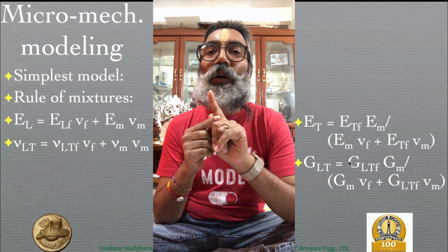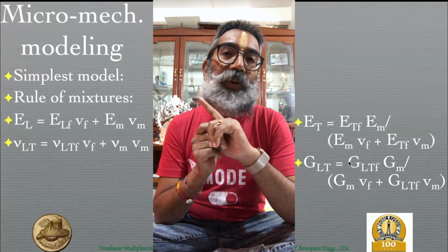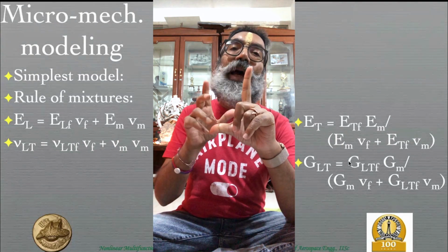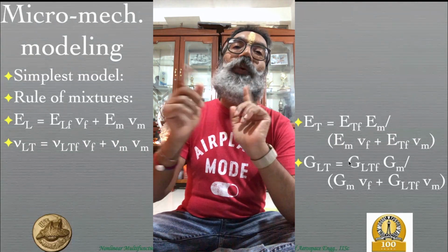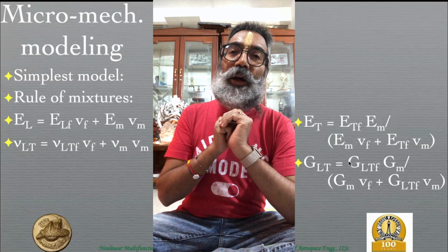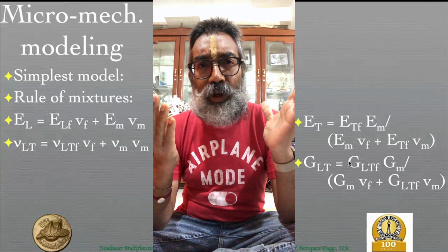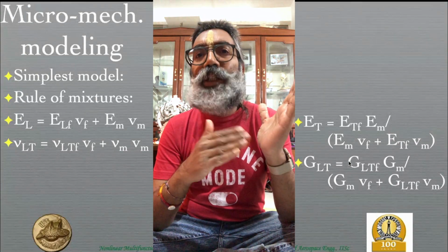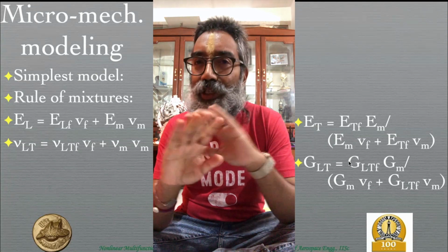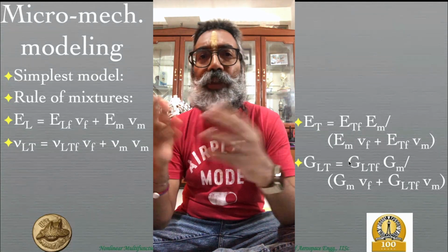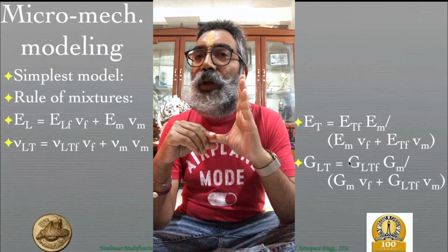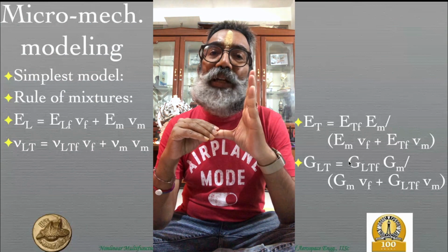As long as these two are not collinear, the change in angle is what we are interested in, and we can always map it to a right angle changing its angle by a certain amount, and those two will be related to each other to some extent. So you'll have to derive that geometric equation. See, this is basically strain versus displacement or rotation. So it's entirely geometry. The material is playing no part here, whether it's a composite, whether it's a metal, it doesn't matter. It's pure geometry that we are talking about in a 3D Euclidean space that we are now dealing with.